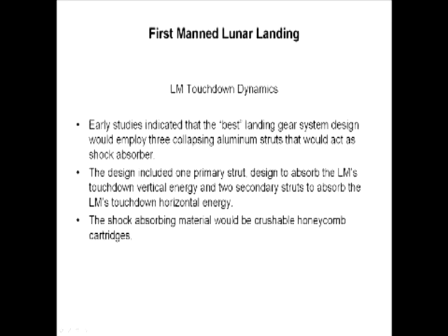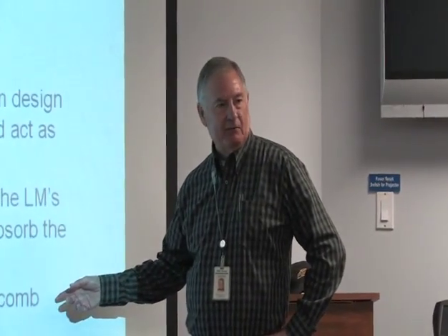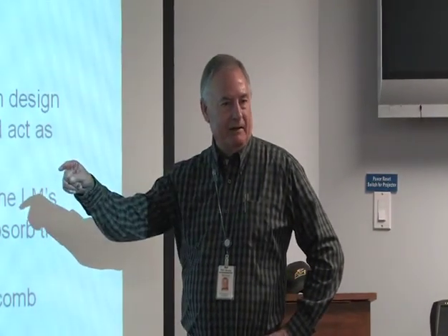They had tension. If it was being extended, we had about 500 pounds for about 4 inches of the honeycomb collapsing at 500 pounds, and then it would go on up to something like 3,000, 4,000 pounds. And by the way, in our testing, we couldn't get them to give us precision honeycomb like they're going to put in the real LM.